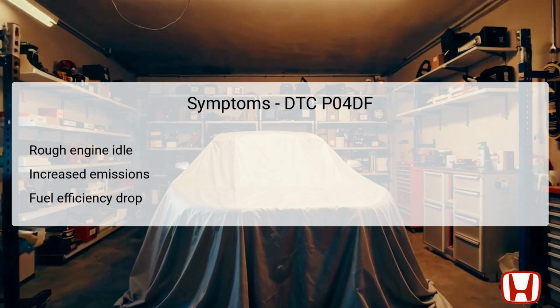Recognizing the symptoms associated with DTC P04DF can significantly aid in diagnosing the underlying issue effectively. One common symptom is a rough engine idle, which may occur due to improper air-fuel mixture resulting from malfunctioning EVAP components. Another concern is increased emissions.